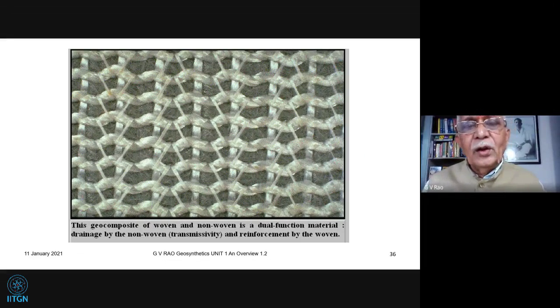So what did we say till now? We said there are two ways of making a non-woven geotextile. One is a weaving process, another is a needle punching process. Okay. From the needle punching, we also got into, let us say, thermal processing, or thermally bonded. And then there's also a process called the chemical process, wherein the entire non-woven geotextile is actually put into a resin, hot resin, taken out, as in squeezed out, and it becomes, you can say, a chemically bonded one. That is not so much in use, so I just dispensed it. So there are three kinds of non-woven geotextiles: mechanically bonded or needle punch, thermally bonded, and chemically bonded. Chemically bonded we ignore because it actually closes all the openings which are there, so it's useless for us. So we are not going to discuss that.